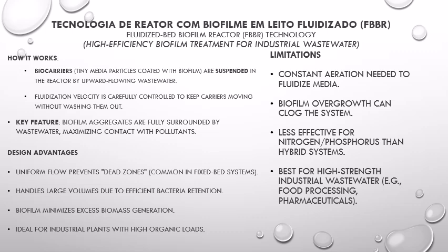So the next method is the fluidized bed biofilm reactor technology. This is a high efficiency biofilm treatment for industrial wastewater. How it works is the use of biocarriers, tiny media particles coated with biofilm, which are suspended in the reactor by upward flowing wastewater. Fluidization velocity is carefully controlled to keep carriers moving without washing them out.